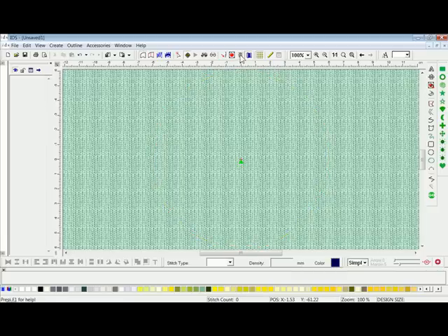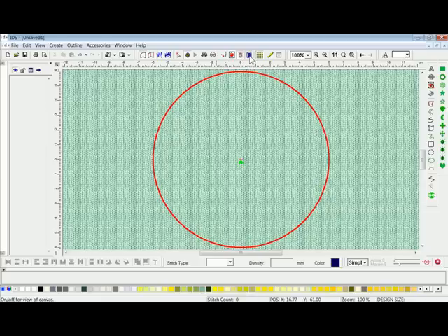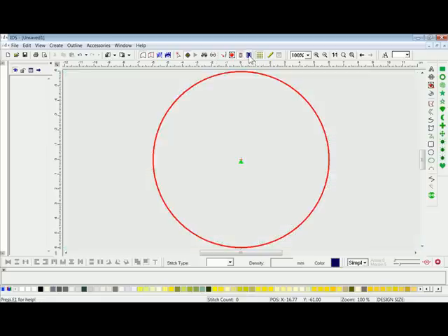With that left clicked, the hoop is not showing. You can also turn off the canvas in the background by the hide view canvas icon. When we click on hide the canvas, we can see that instead of that yellow, we have now changed it to gray. We can also change the viewing of the grid with the hide view grid, so we can turn that grid on or off.